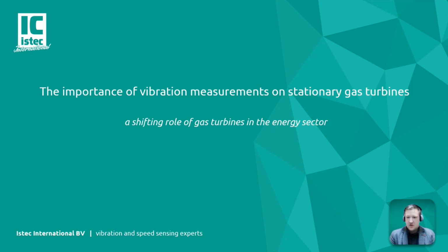What we see is that the energy landscape is changing significantly. Where turbines initially ran mainly on base load, we see more peak shave modes being used. Peak shave involves a lot more start-stop cycles, which put more strain on the turbo machinery, and therefore wear and tear are increasing.